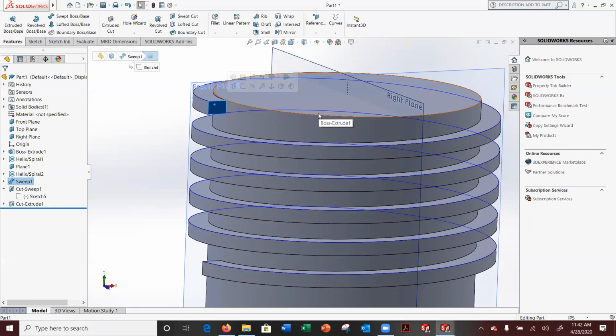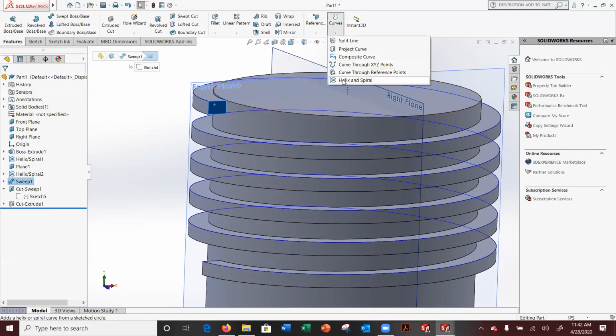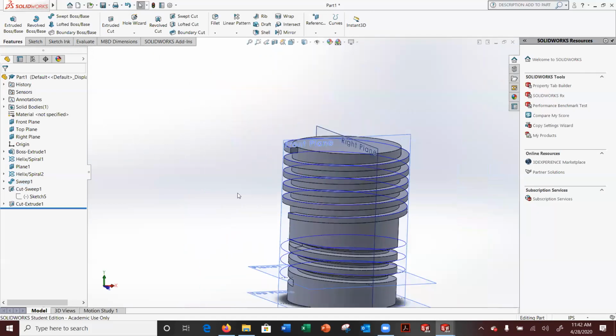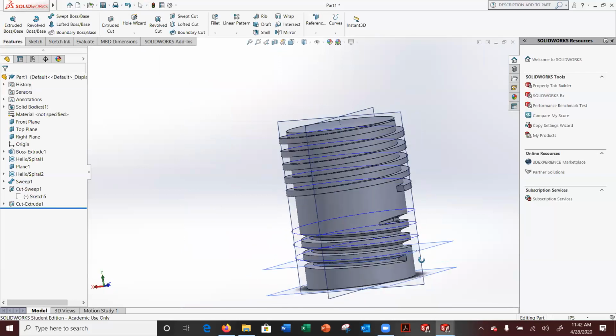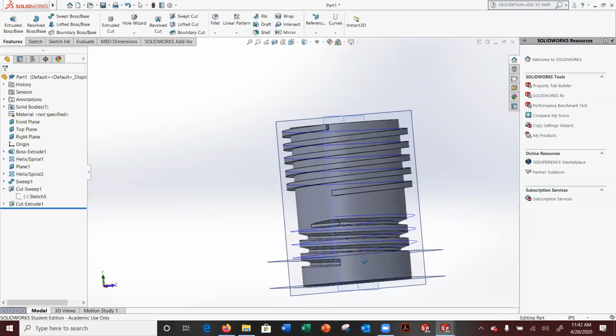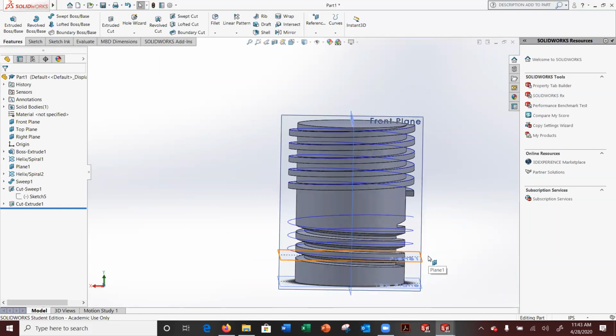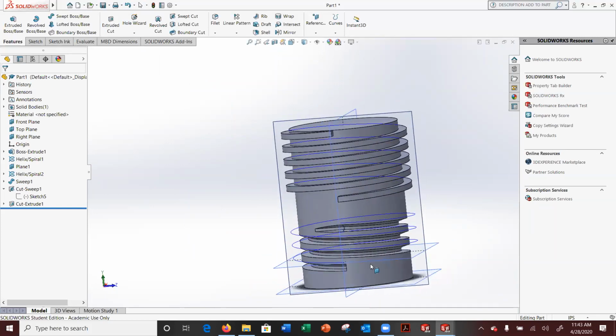Another approach some people have taken is you just basically create your helix off the part so that way it cuts in neatly. So there's a couple of ways to get around abrupt endings. In this case, they're inside the part, so you can't avoid it. Hopefully this helps you when you're making threads, internal threads as well as external threads, making cuts of any type.